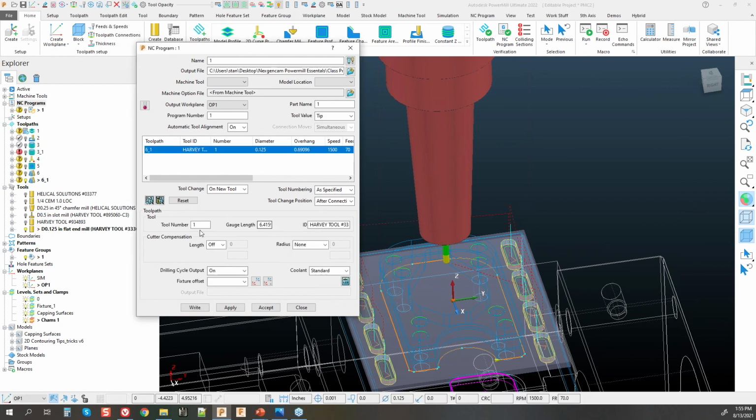the toolpath itself actually has options within here for compensation. Now, the downside to this is that you don't get the preview option. So if your lead in, lead out isn't quite correct and doesn't have the extent to actually apply the lead in your code, in the case of Haas and some Fanuc machines in most cases, then you won't actually get that. But once I add that compensation, I'm then able to turn that on, and then that will post out in code separately. So we'll have cutter compensation on our swarf toolpaths, if you will.